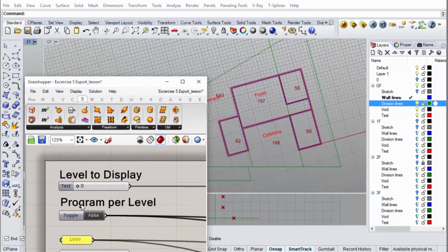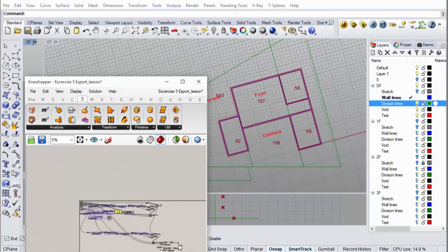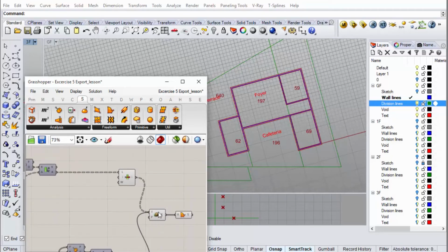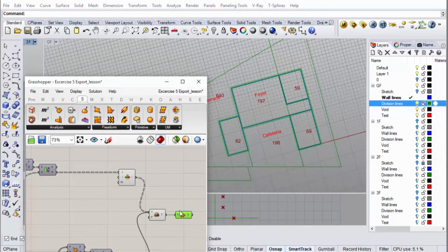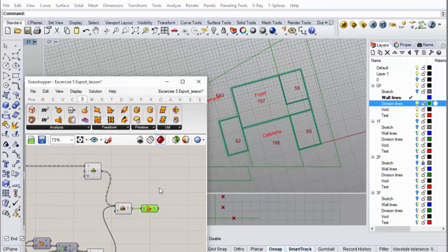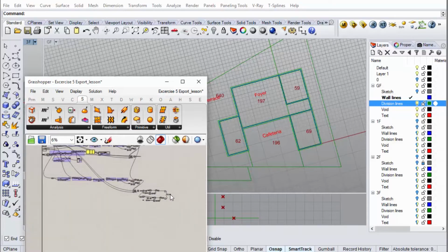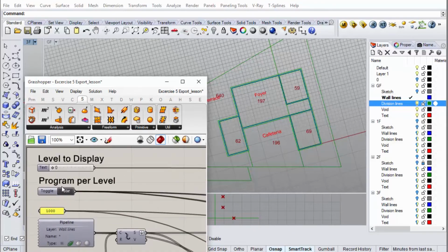And so all of this is quite easy to export. You can export the individual curves by baking this, or you can export the surfaces by baking this, and then you can either hatch this or possibly export these curves and then extrude them. Or what we could even do is turn this on and have all of them be calculated.